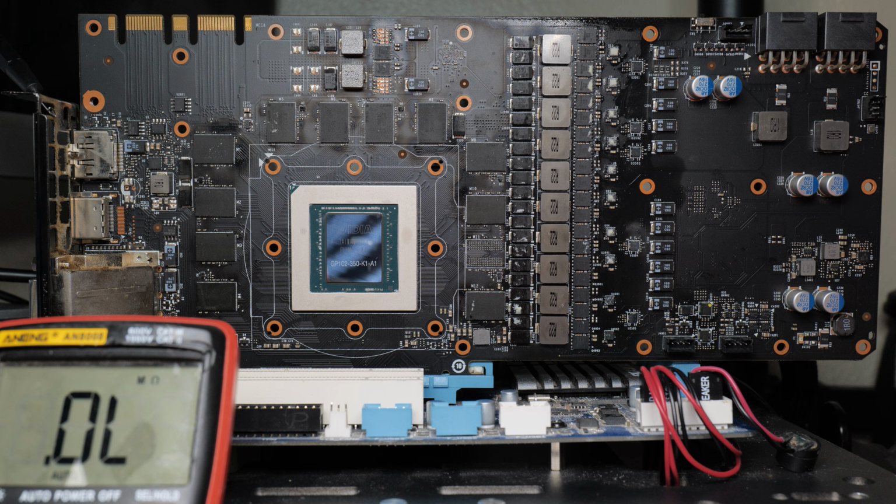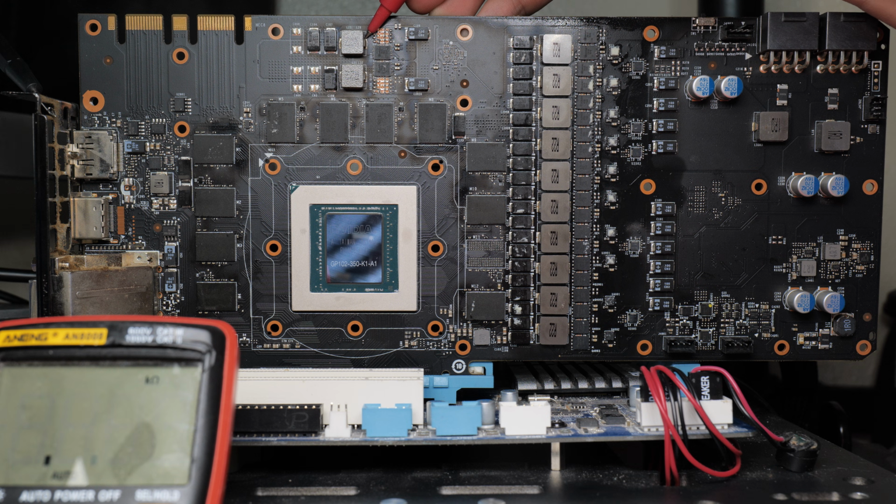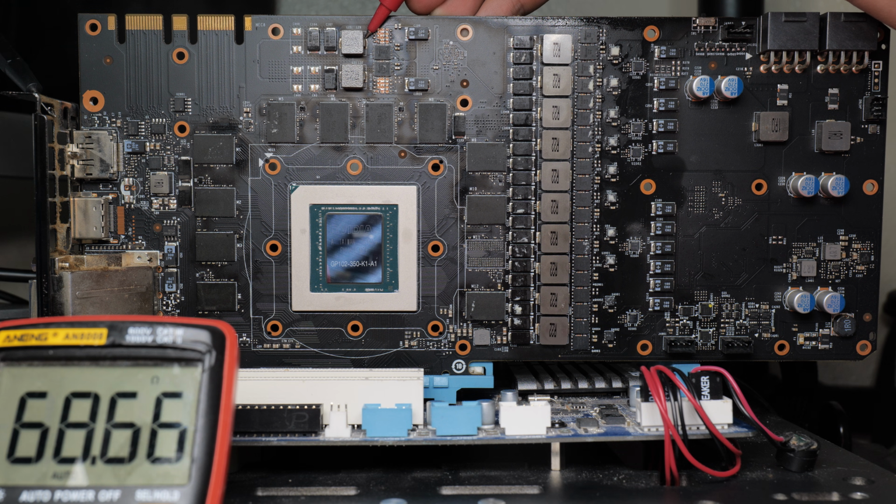So for a card with memory-related errors, there are two things that you want to check, or at least for this card there are two things, but at least one thing on all other cards. The first thing you want to check is the memory phase itself, as sometimes when you have a faulty memory bank, the memory bank itself goes short, or the memory controller ends up being the source of a short. But in this case, we have 68, 69 ohms, which is perfectly fine.